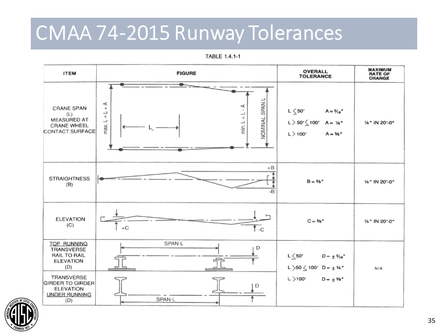With regard to expansion in a building, that's an extremely good question. I have not actually seen any effective way to transfer or to maintain a clearance between discontinuous runway members at a building expansion joint. That's an extremely difficult thing to maintain.